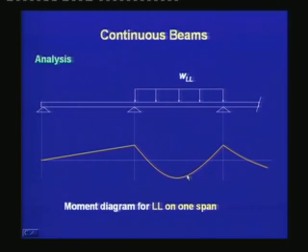The third case what we are seeing is due to the live load in one intermediate span. Here we haven't placed any live load at the end span, and for this the moment diagram is that throughout the end span the moment is negative. This is unlike the bending moment diagrams due to the uniform live load, where it had created positive moment in the end span.